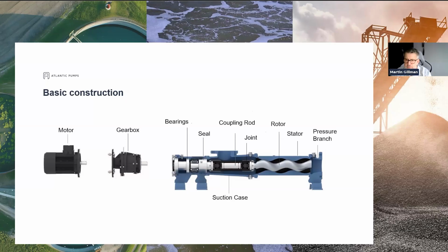Very common out there in the field, for those of you that are used to dealing with things on the front line: if a pump appears to be not performing, we assume that it's worn out, so we'll spend lots of money changing the front end here, when all along it could have been the seal that was beginning to fail and sucking in air, and it could be quite a lot of air. So our flow meter is telling us the truth, but it's not actually because the pump is down on efficiency, volumetrically that is. It's because we're putting in lots of air. Sometimes it can be spotted because your flow meter is jumping around a little bit and it's not particularly stable because of the amount of air going through, but just point that out while we're here.